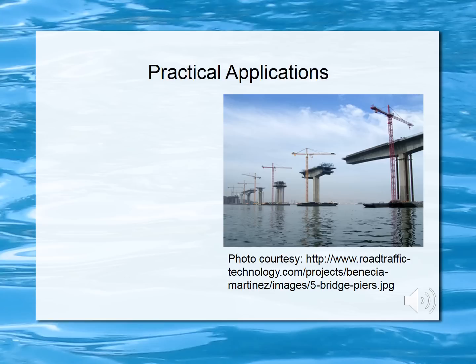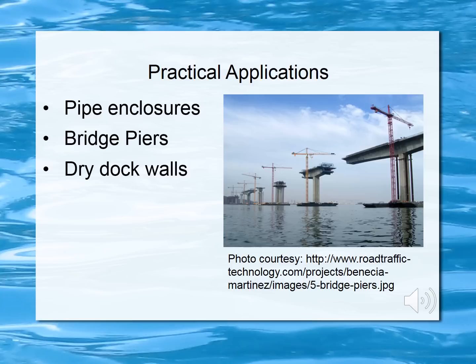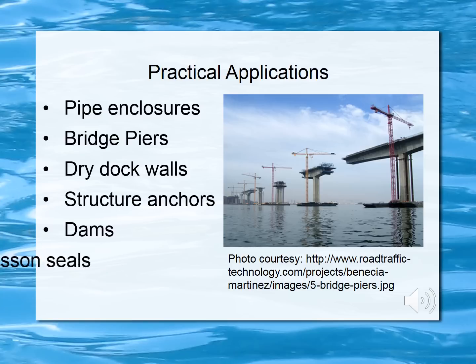Some practical applications, the things that you would use underwater concreting for, would be things like pipe enclosures, bridge piers, dry dock walls, structural anchors, dams, and caisson seals.